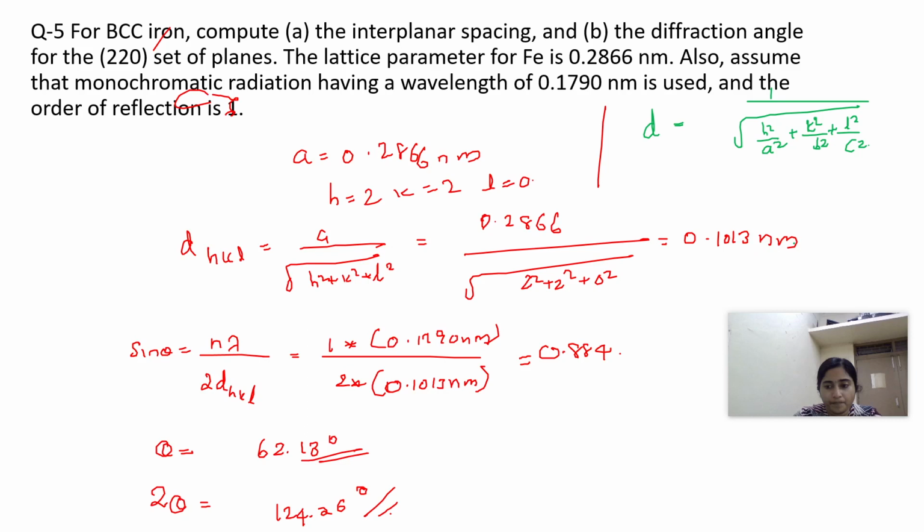That's correct. But let's say we are calculating the interplanar spacing for the 111 plane in a cubic structure. Any of the dimensions will be length, right? Yes, it will be length, but which length? You are actually asking what d is, right?